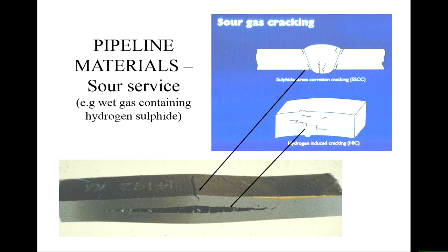If the corrosion is not too bad, just making the pipe a bit thicker using a corrosion allowance is the way that most people would go. It's only as we go into more difficult fields with higher sulfur contents and things that these more difficult analyses become necessary, and we have a driving force towards other steels and even nickel alloys when things are very bad.